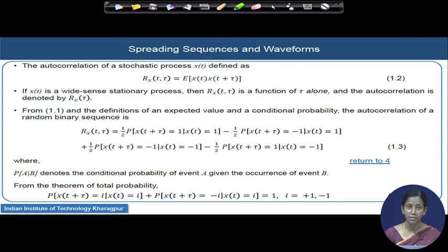This is a typical demand for the autocorrelation property of any spreading sequence, and such sequences are most preferable in our system design because they give very good demodulation. At the end of the despreading, you will get a good difference between the spread signal and the jamming, and your signal energy won't be spread much over the side lobes.